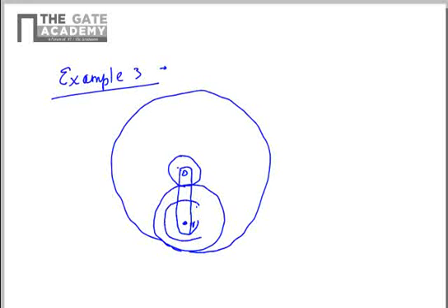The gear C, which is the planet of the first train, and this is gear A, the sun of the first train. Gear C is made to have a compound gearing with gear B. So gears C and B are on the same axis, but gear B is smaller.